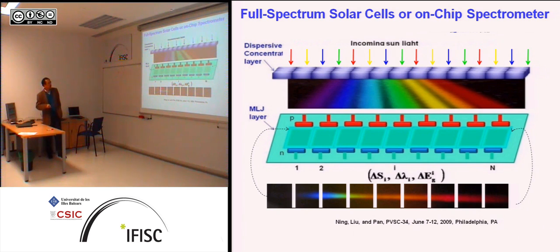This is my composition graded semiconductor nanowire. I can pattern my substrate so that I grow this. This is the length of the sample. I subdivide it into a number of subcells by patterning the substrate. That's straightforward because this growth relies on the catalyst. Where you don't have catalyst, you don't grow wires. For example, you subdivide this into, let's say, 10 cells.